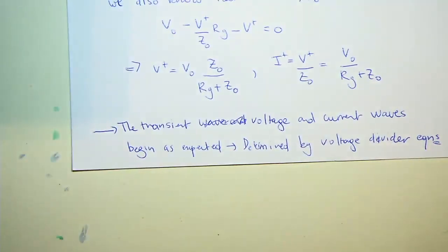Excuse me? Yes? Just at time infinity, do we not consider the impedance of the transmission line? No. And that's why it tends to your first year circuit theory. Okay? Because all of a sudden that characteristic impedance just stops that wave from being able to propagate. But after a sufficiently long time, you neglect that.